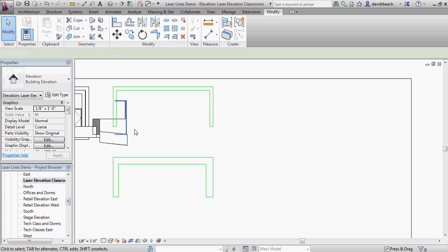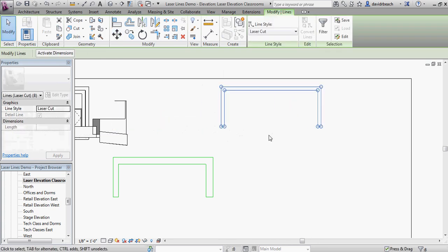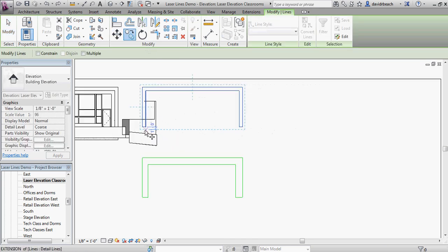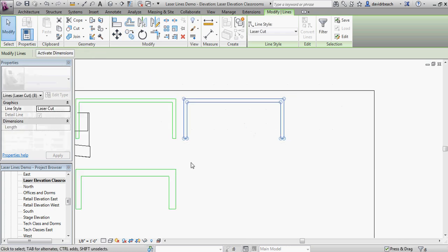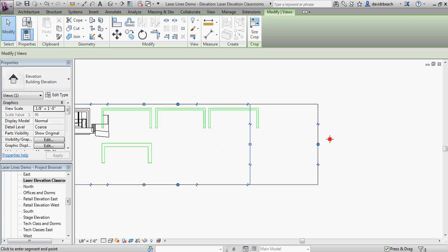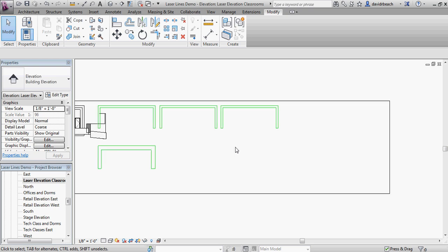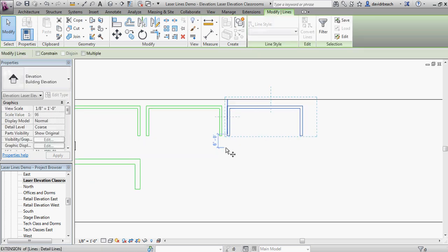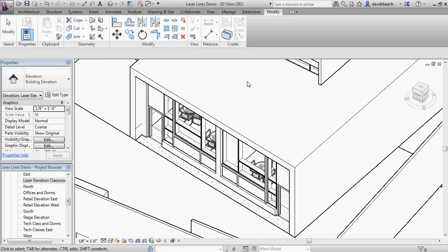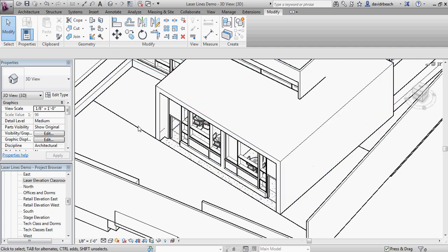Let's say that I actually wanted this piece to happen and stack up several times. So what I want to do is copy this piece over. Let's say I'm working with 1/8 inch chipboard or something close to it, and I wanted this particular element to repeat and get up to 1/2 inch in thickness. So I'd need 4 of that particular layer to stack up. Let's go back to the 3D view. What that gives me is this piece coming off of the page a little bit.